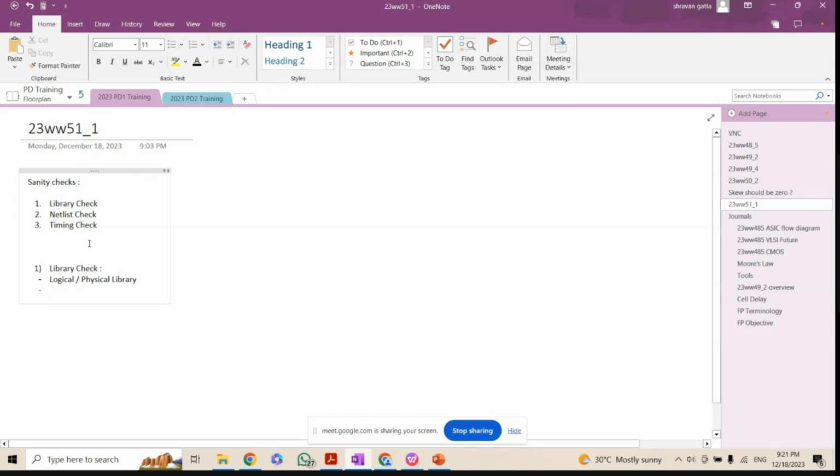If we have floating inputs, our functionality will fail, and it will also cause glitches, and dynamic power consumption will increase. And the main point: the cell will go into the metastability stage.